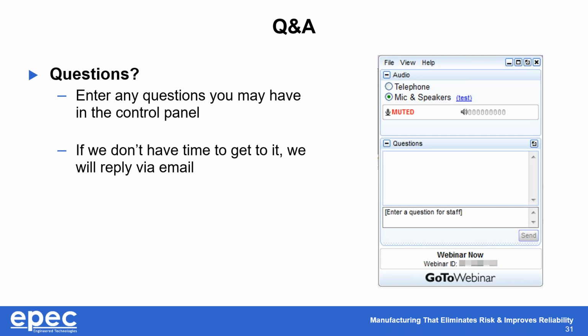Shield layers have a slip property to the external coating of the shield layer. So as such, you can't laminate anything on top of a shield layer. So shield layers cannot extend underneath stiffeners, for example. Because shield layers are applied on top of the cover lay, you need to account for material and manufacturing tolerances. So openings in the shield layer surrounding surface mount components, as an example, need to be sized accordingly to take into account all of the involved material and manufacturing tolerances.